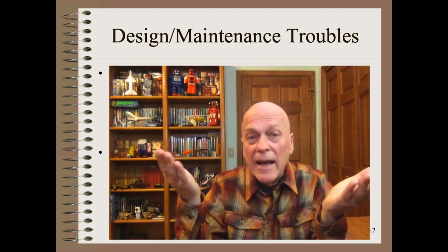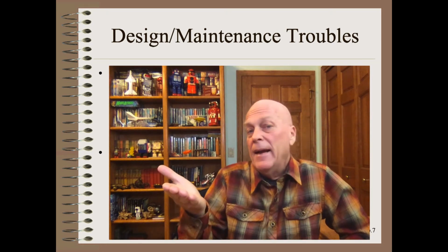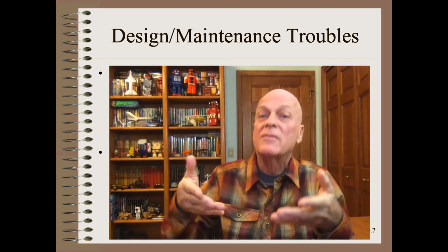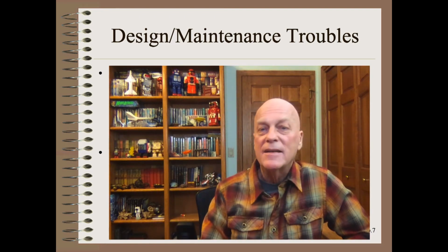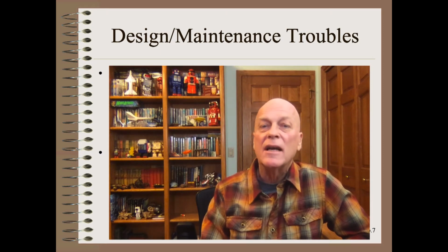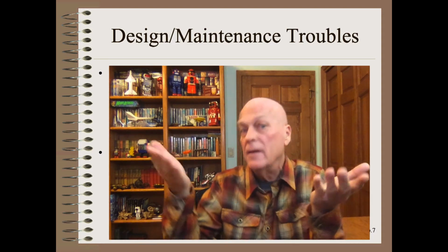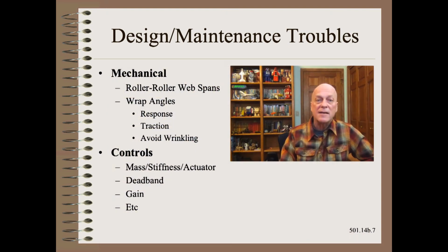However, merely adding a guide may not solve path control problems. In fact, adding a guide without attending to the details may make path control problems worse, and in addition may cause wrinkling, web breaks, and other troubles. I've seen hundreds of guides in the metals, paper, textiles, and converting industry that fall into the category of making problems unnecessarily worse. There are many details for the mechanical designer to consider when laying out the web path.